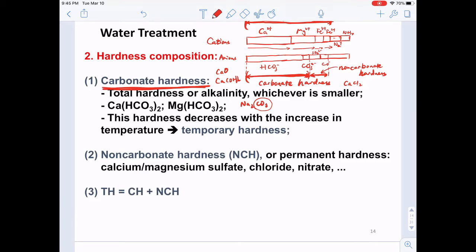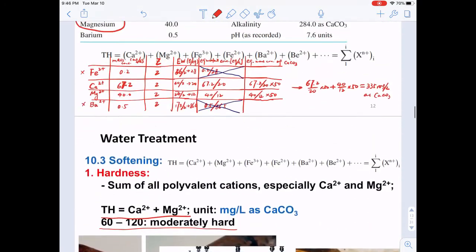So there's another situation, where we can have a lot of alkalinity here. Up here, let's say the hardness is just this long, calcium and magnesium, while the remaining ions are sodium. Under this situation, you can see that the total hardness is just this long here, right? And we won't use alkalinity as the hardness, simply because the sodium is not contributing to the hardness of water.